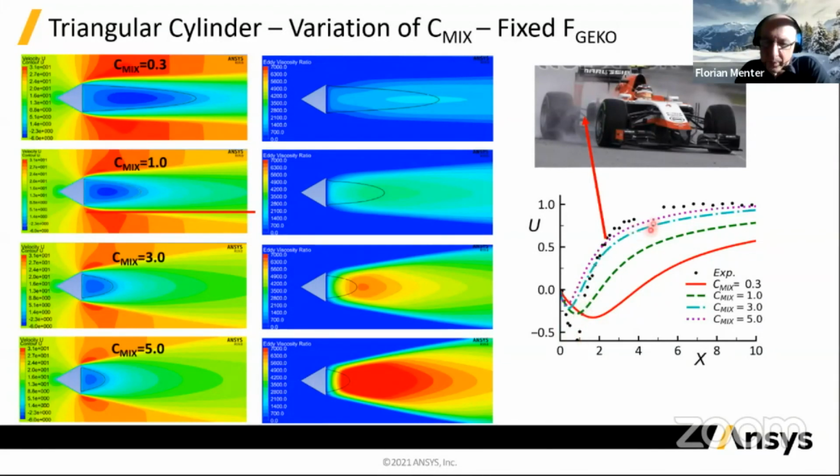But in this case, it would be important to get the proper inflow to the back wheel, for example, and then it's much better to have that level here than to have this very low level of velocity, which would severely affect the downstream area. So this is something which is clearly somewhat outside the envelope of RANS modeling, but you can still force the model to capture at least the main effect of this mixing area there.